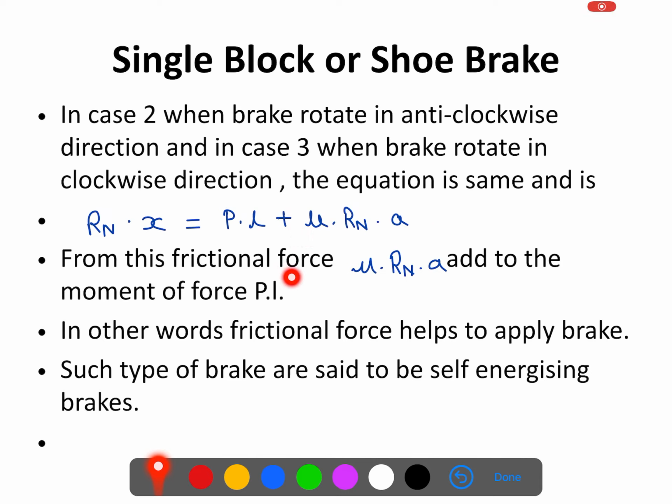From this, the frictional force mu into Rn adds to the moment of force PL. From this what we came to know is that P into L is the moment which we are applying to apply the brake, or P is the force which we are applying on the brake pedal, right?